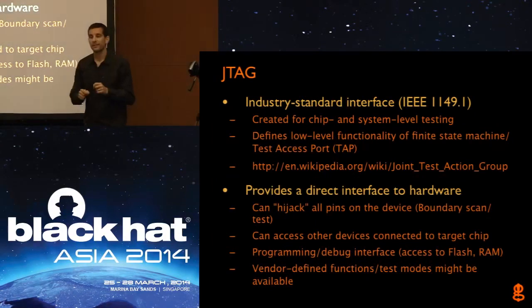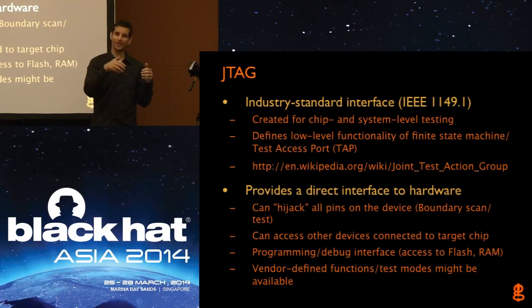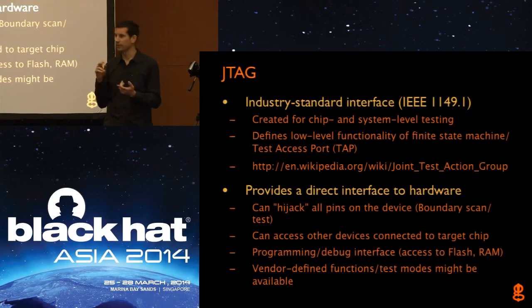of each pin. So if you can twiddle all of those pins, you can now potentially communicate with other things that are connected to that device that you're twiddling, which is how you can program external memory through controlling a chip in JTAG. Also, most devices now have internal memory, so you can access internal memory through JTAG. So you can do standard programming, standard debugging.